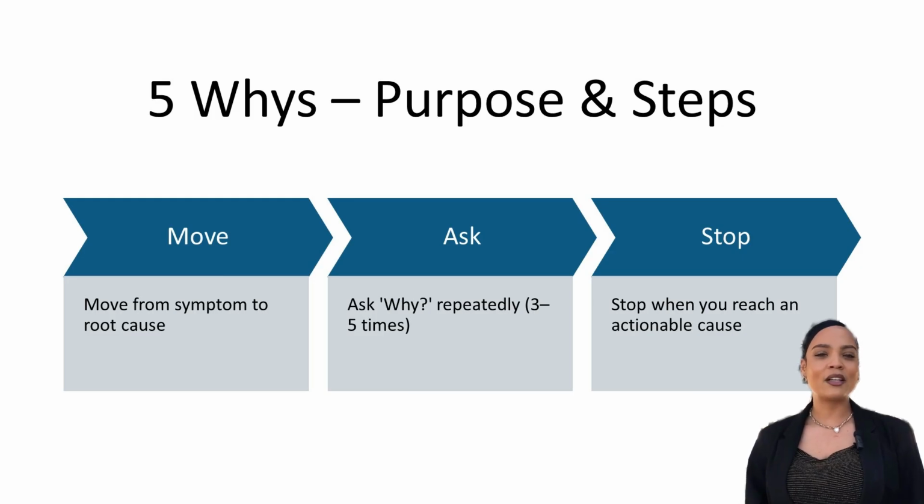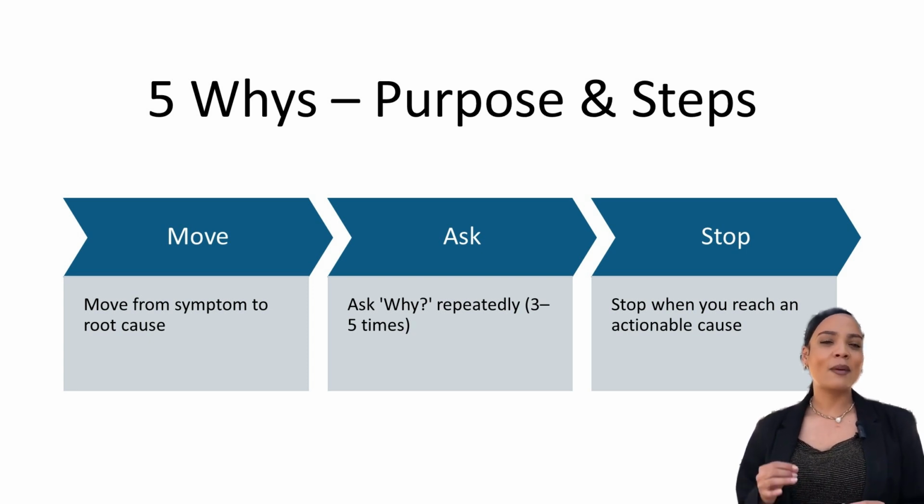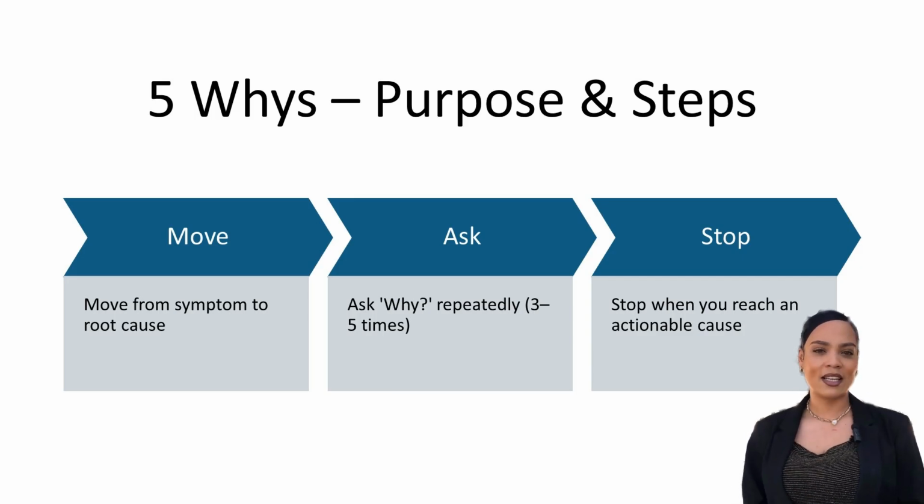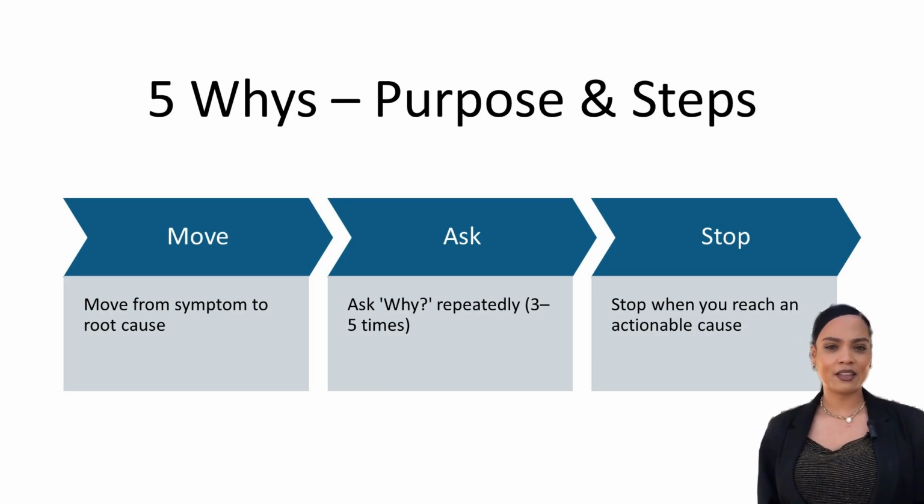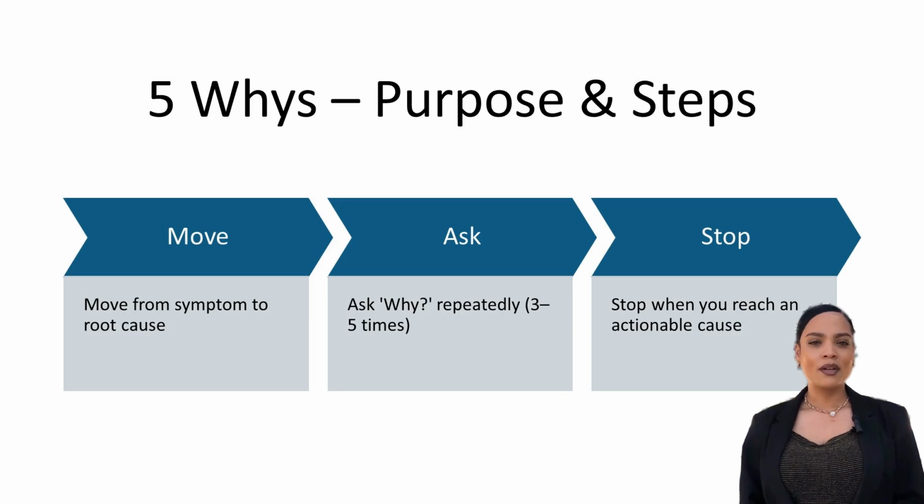1. Purpose of the 5 whys. The purpose of the 5 whys is to move from symptom to root cause. Instead of stopping at the first answer, we keep going deeper. This prevents us from wasting time fixing symptoms while the real cause remains untouched. For example, if a machine stops, the first why might reveal that a fuse blew. But if we stop there, we will simply replace the fuse. By continuing to ask why, we might discover poor maintenance, overloading, or incorrect installation is the real issue.